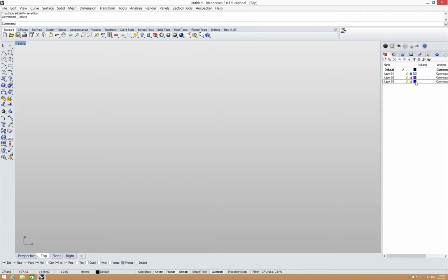It depends on the template that you use, but sometimes you'll see just the default. There'll always be a default when you open up a new drawing. But then there could be none of these additional layers, or perhaps up to 5 of these different additional layers. So these are how we can organize our groups. Kind of think about it as tracing paper over the top of one another. It's very, very helpful in developing complex models, so we'll use them quite frequently.